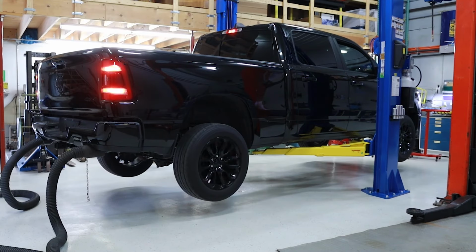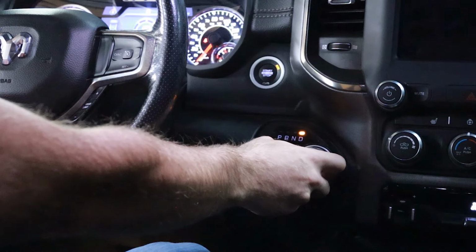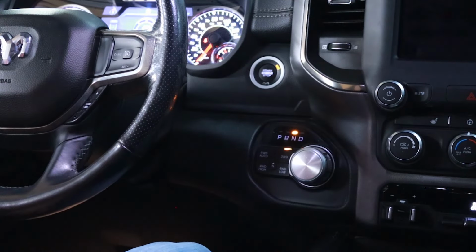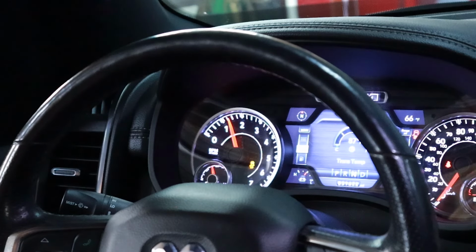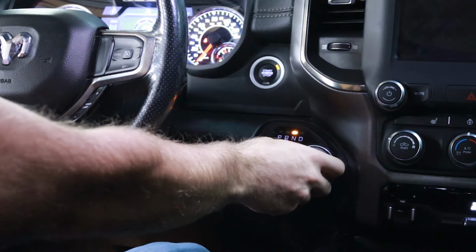Next, release the brake pedal and lightly accelerate the engine, allowing the transmission to shift into second gear. Continue in second gear for 5 seconds. Release the accelerator pedal, gently apply the brake pedal so the wheels stop rotating. Then shift the transmission into neutral. With the transmission still in neutral, bring the engine up to 2000 RPM for 5 seconds. Then lower the RPM back down to idle. Gently apply the brake pedal and shift the transmission back into park.